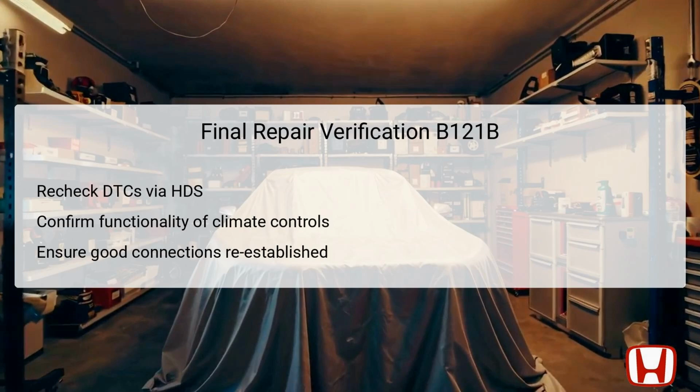After undertaking the necessary repairs to resolve the DTC B121B issue, it is critical to conduct a final verification. Begin by rechecking for any remaining DTCs via the Honda Diagnostics system. The process will confirm whether the repairs executed were successful in eliminating the error.